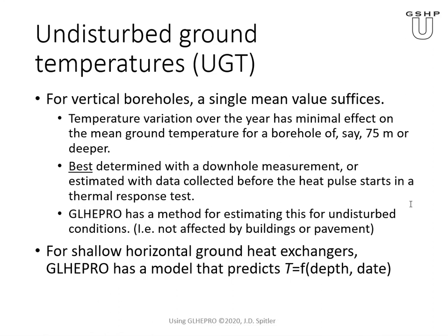Another way of approximating this is, typically when we do a thermal response test, we'll start circulating the fluid, so the only energy going in at that point is the circulating pump. And if you record the data frequently, for say 3 or 4 times circulating through, you take the average of the temperatures that you measured, you get a reasonable idea of the undisturbed ground temperature. That's another way to do it.